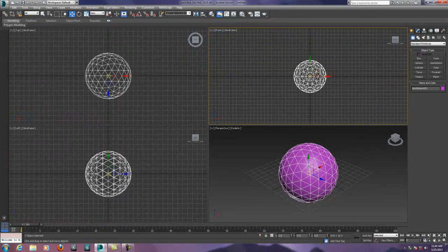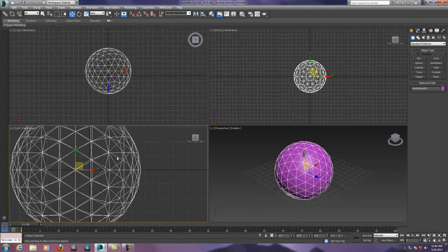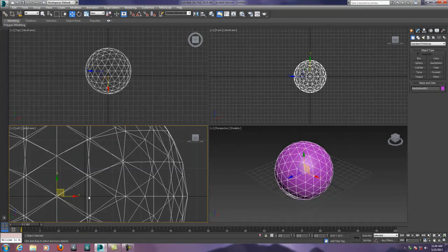When you click an object and you go into the move command, an object here will have a Y and an X direction. We don't see the Z because the Z is coming at us. But if I look at the Y, I can come over here where it says Y and type in 10. And you'll notice that it moved in the Y direction 10 spaces. Now over here in the left view, you'll see that it came off this direction. And you're probably like, wait a minute, you typed in Y. The Y is up and down.